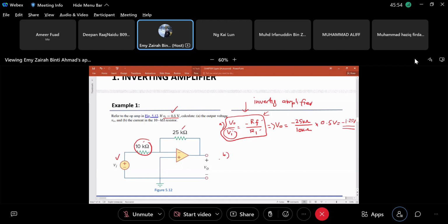So the current, remember earlier we derived at this point, let's say point Y. Current flow through here equals current flow through the feedback resistor. Let's say we make it IF. I supply, let's say the current here equals 0, so we do not consider this one. So IS is the current that flows through the 10 kilo ohm, right? This branch is IS, up to here IS. After this point it divides into IF and I entering the amplifier.